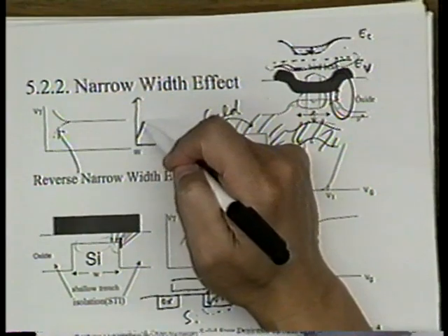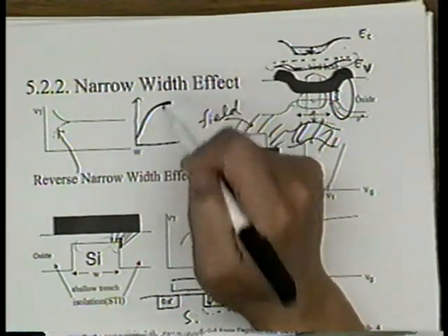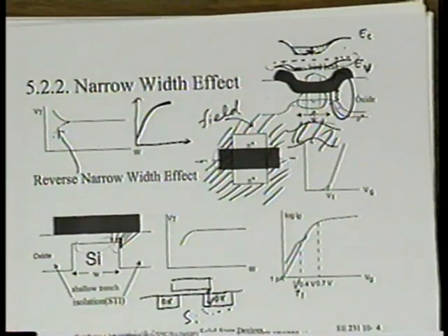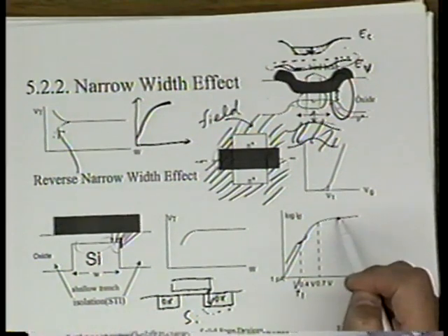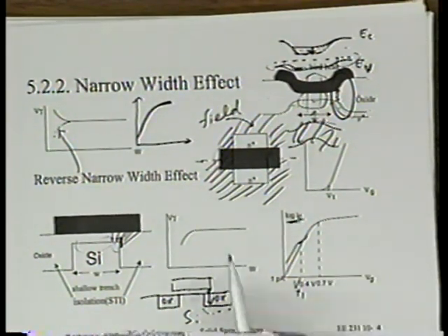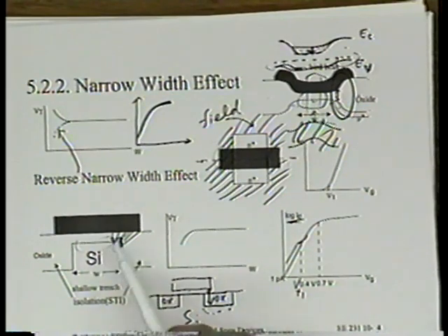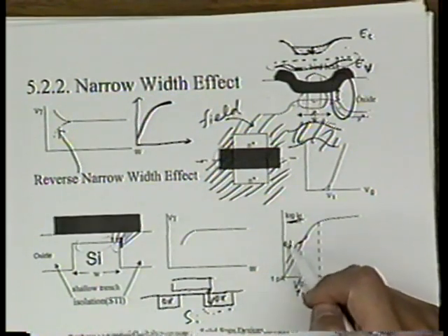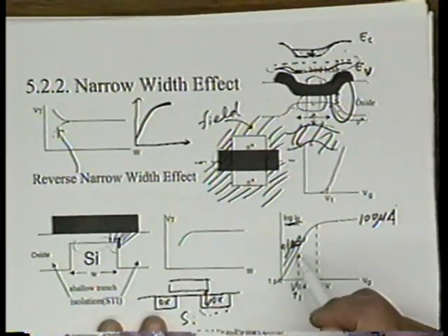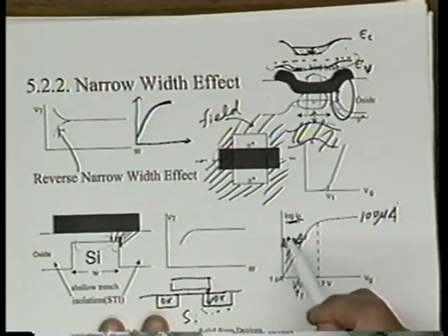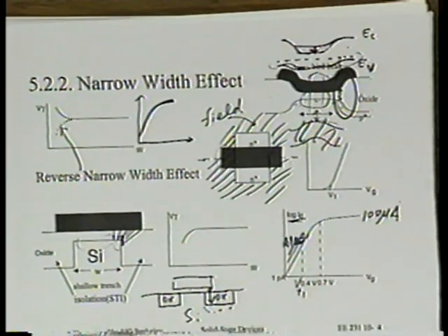Do you agree that it will look like that? That is, first we see the main channel turning on. Then we will see the new transistor turn on. But which of these two transistors conducts more current? Earlier I said this probably saturates at a much lower value than that. Remember this is a log scale. Because this corner is very small compared to the bulk, suppose this is 0.1 microamp, usually smaller than that, and this is, let's say, 100 microamp. At 0.1 microamp, we start to see one corner. At 100 microamp, we see a corner.